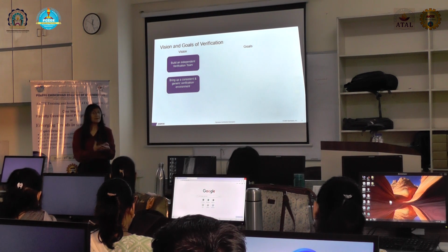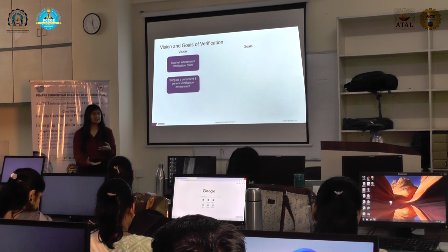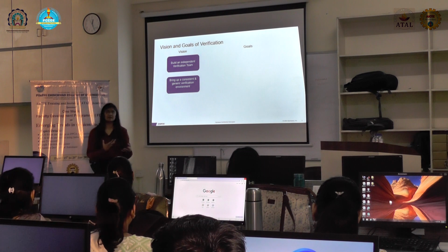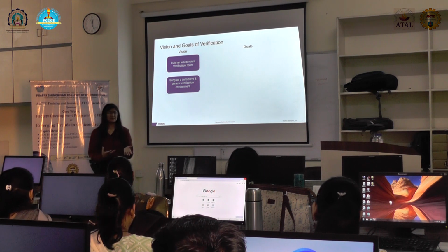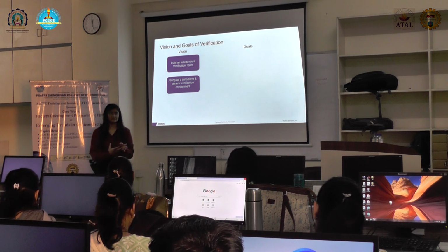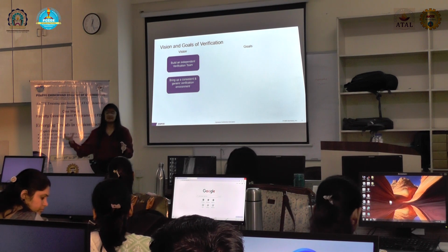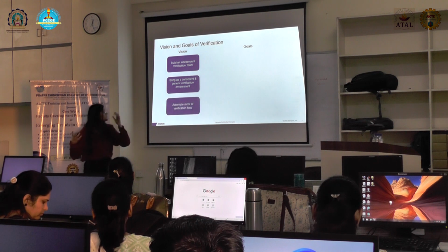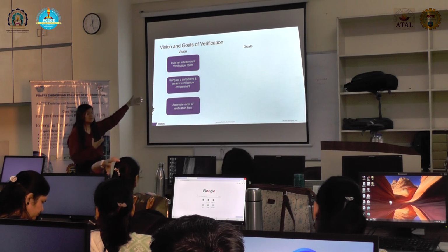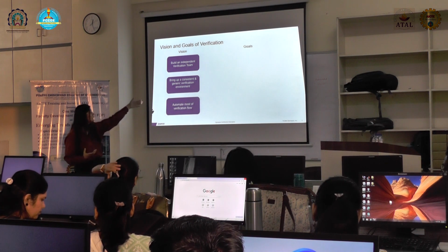Object-oriented programming, randomization, coverage collection, those features are not there in Verilog. There is some randomization, but it's not at the level that we require for verifying any specific product. So that is part of the generic environment build-up that we require.